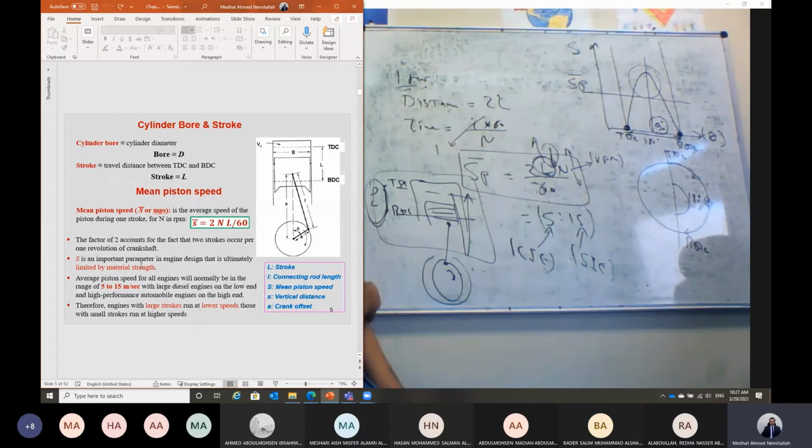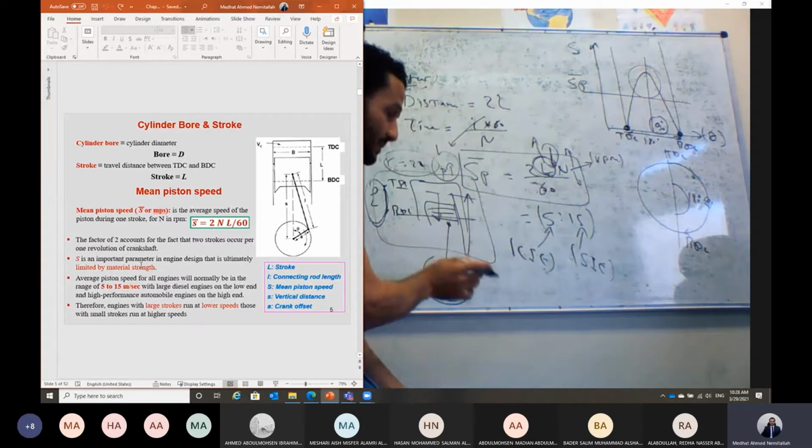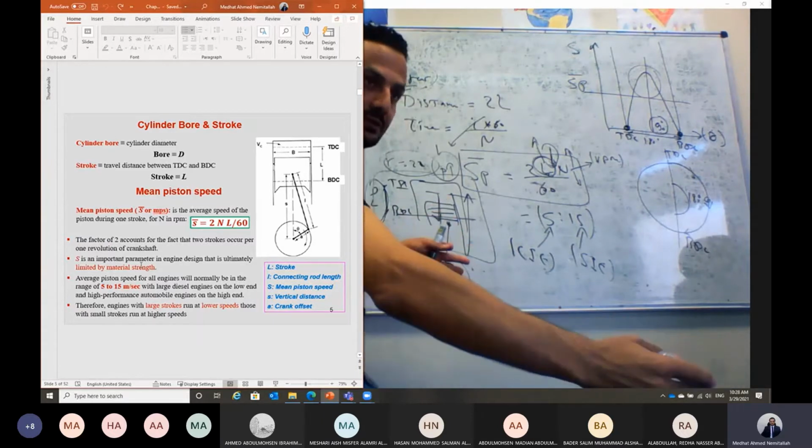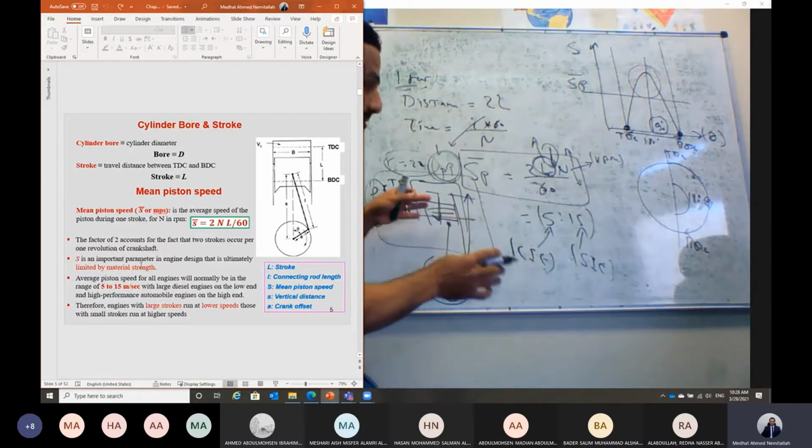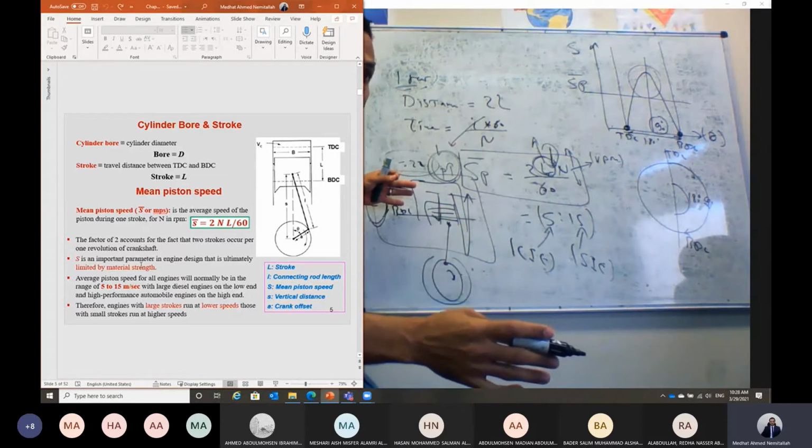For combustion, doctor. It's related to combustion. In the case of a diesel engine, the compression ratio can approach a value of 22. That will create very high pressure inside the cylinder. So during the expansion stroke, we need the piston to travel a longer distance until we can reduce this pressure and benefit from the expansion of all of this high pressure.